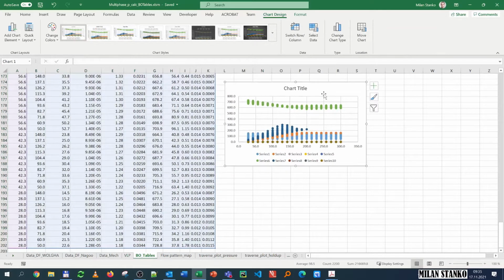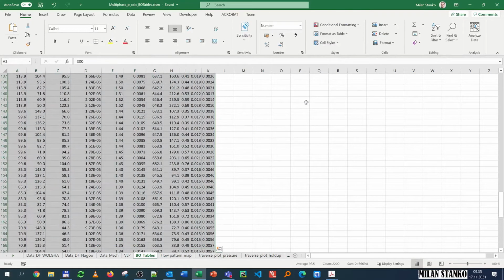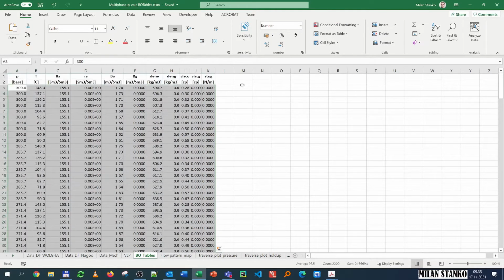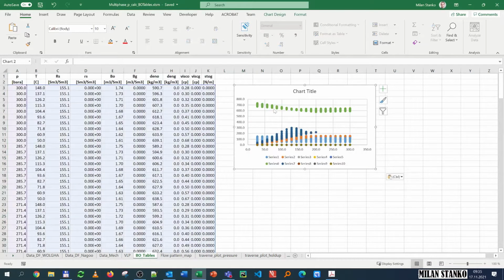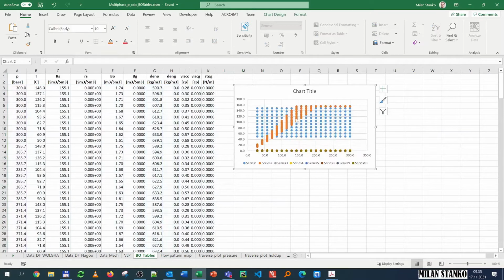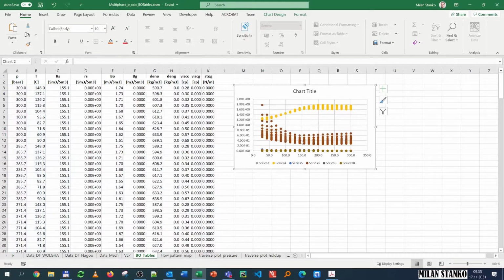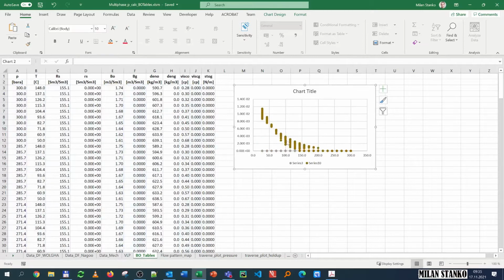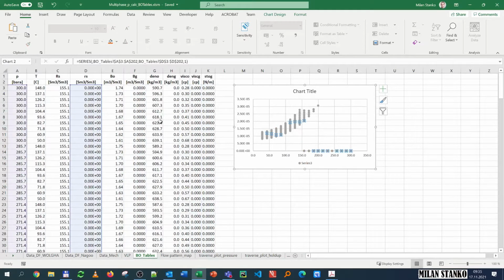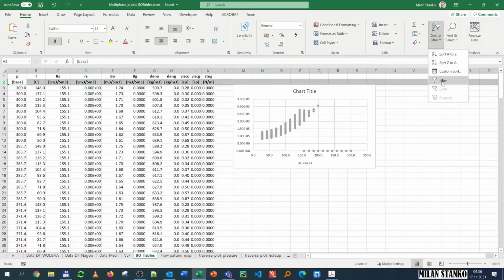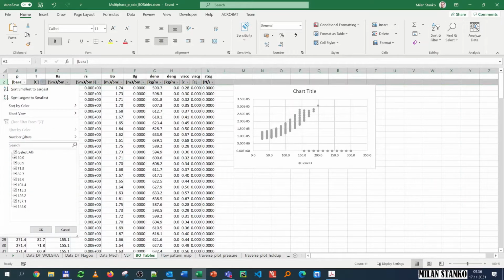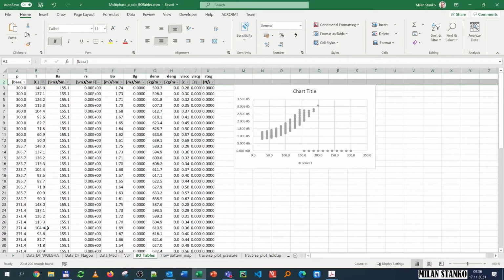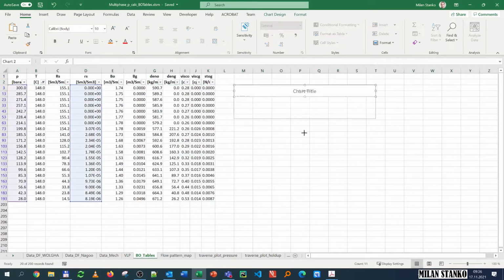Okay, so let's first take all of these and we want to make a plot. Okay, and let's put it all the way to the top. Okay, and then we're going to just remove. We don't need so many. We could inspect all of them at the same time. Okay, we're going to leave just one series. In this case is small rs and p. And now we're going to apply a filter, and we're going to say we want to see the data only for a given temperature. Here we have a lot of temperatures, so let's see for this temperature 150. How does it look like?